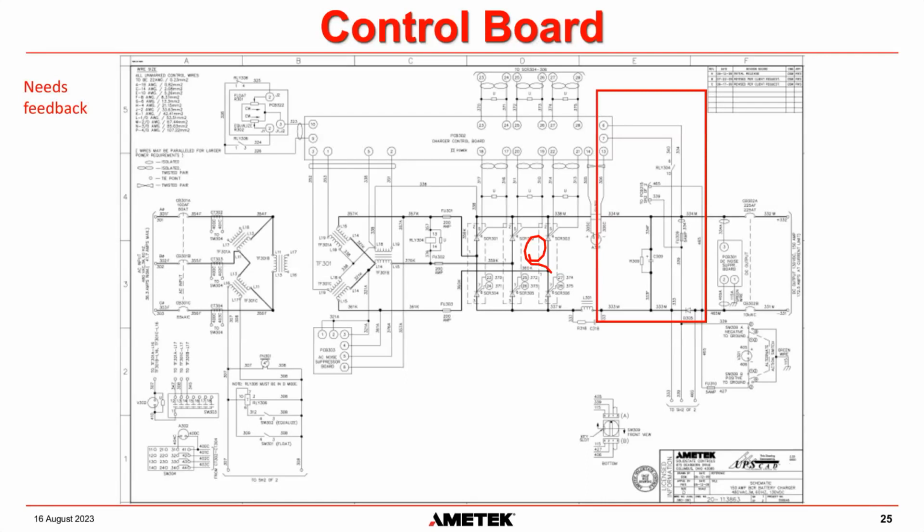So for example, in most of our chargers, that's going to be around about 135 volts DC. So that charger is expecting to see a 135 volt DC signal going into the board there. If the voltage goes down, the SCRs will turn on more to make the voltage go back up again. If the voltage goes up, the SCRs will turn on less to allow the voltage to go down. It's a constant feedback loop that is happening all of the time.